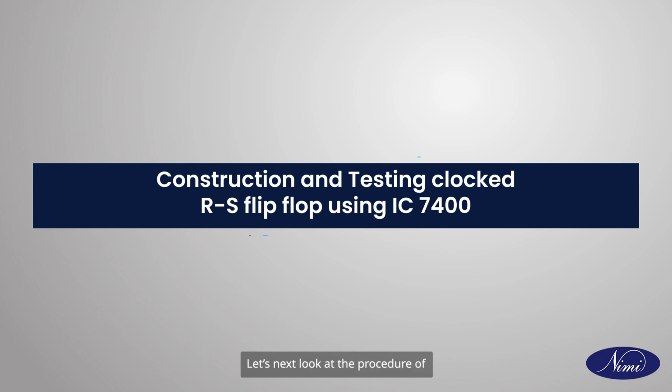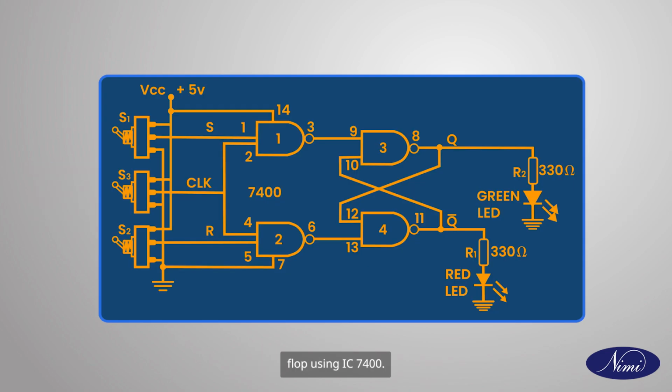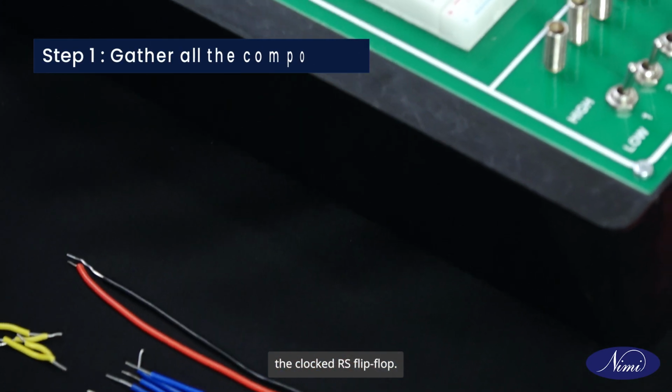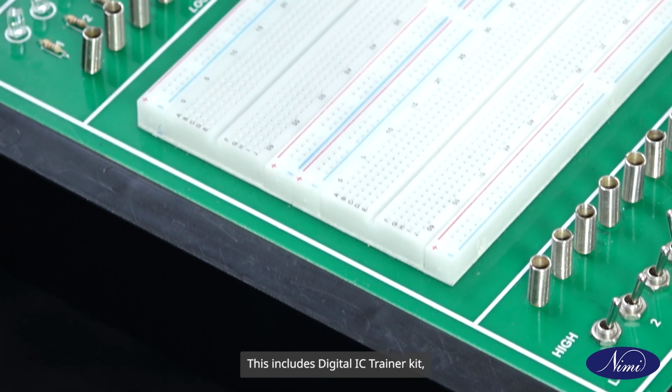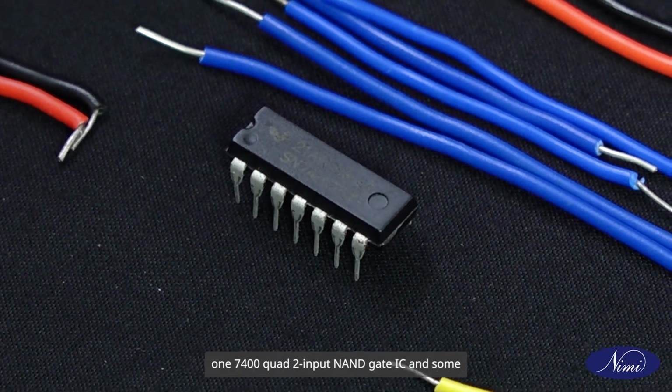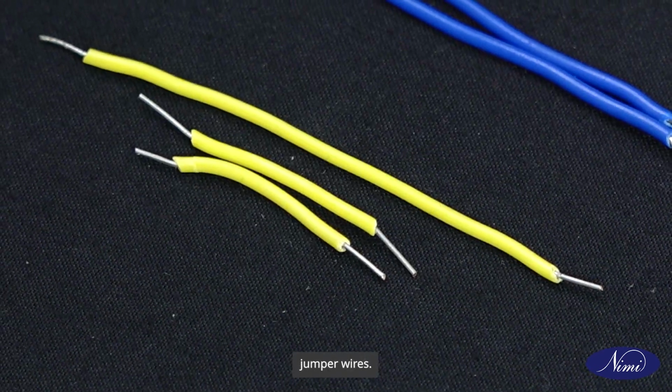Let's now look at the procedure of construction and testing a clocked RS flip-flop using IC 7400. Collect all the required components to build the clocked RS flip-flop. This includes the digital IC trainer kit, one 7400 quad 2 input NAND gate IC and some jumper wires.